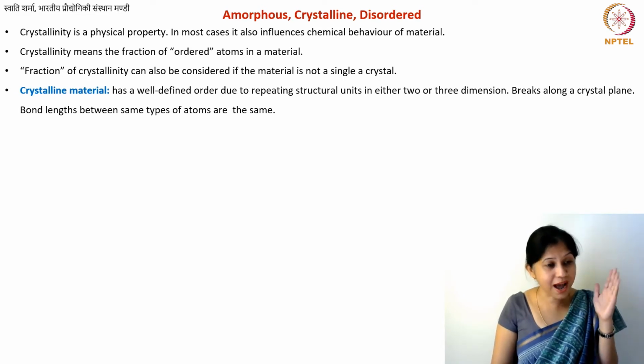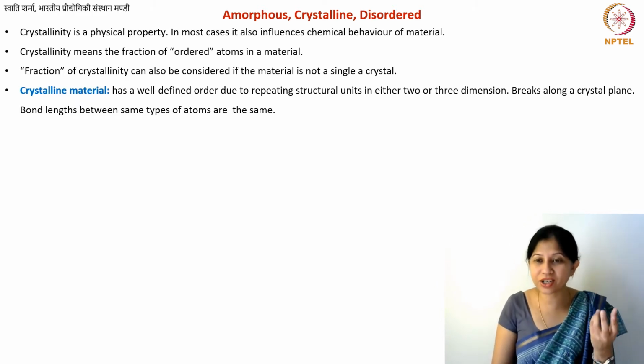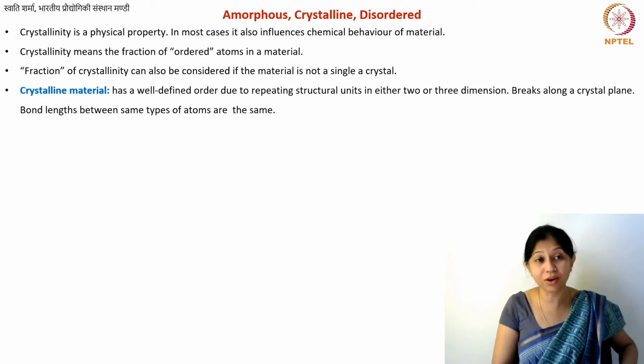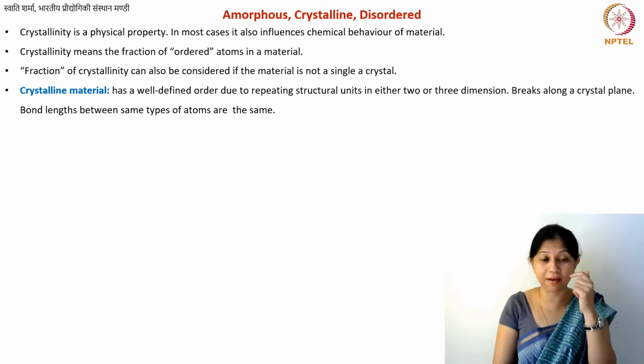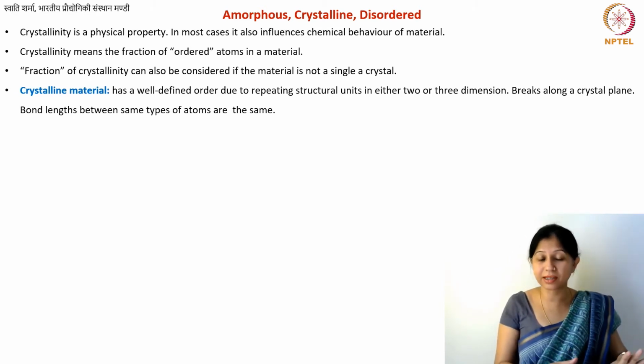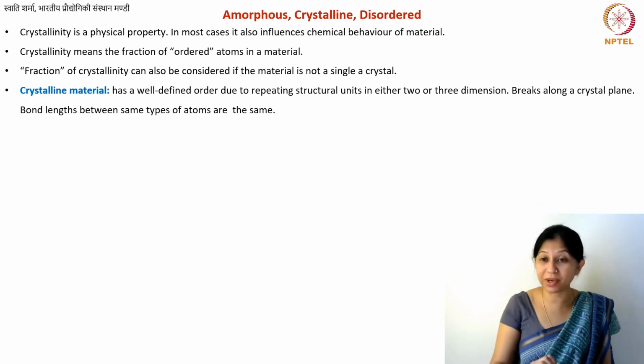But what you can have is partial crystallinity, or a certain fraction of the material which is ordered, like you also saw in the case of semicrystalline materials. But also you can have this kind of order in elemental materials, not just in polymers. In the case of semicrystalline polymers, you saw that there are chain-like molecules, but you don't necessarily need chain-like molecules to have fractional crystallinity. So some part of your material is crystalline and the rest is, what is it? Well, let's just call it non-crystalline. The term amorphous needs to be used very carefully.